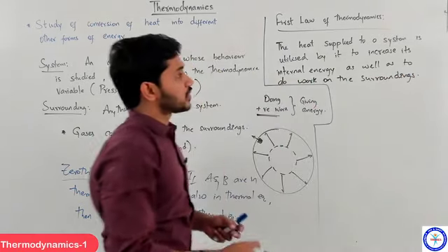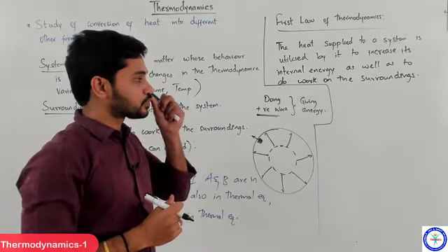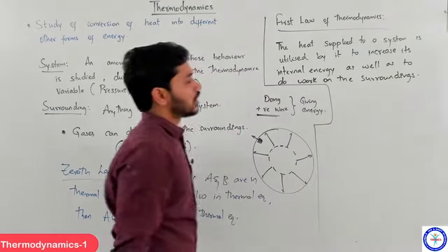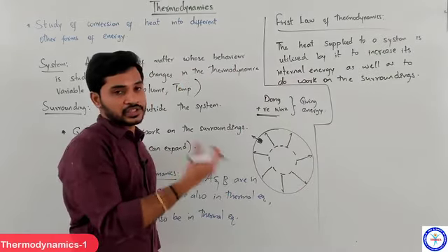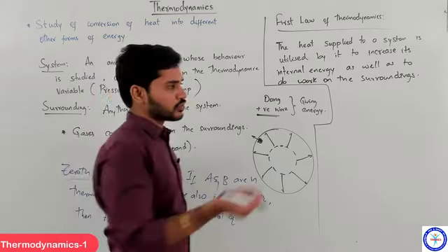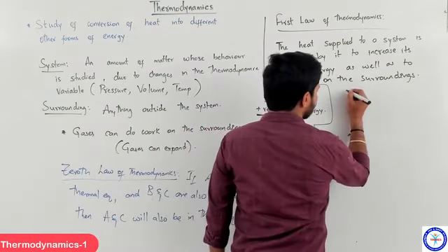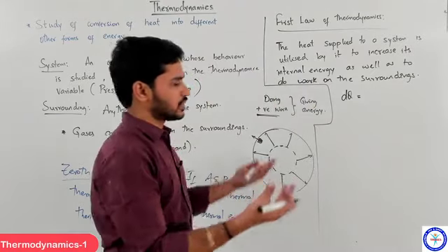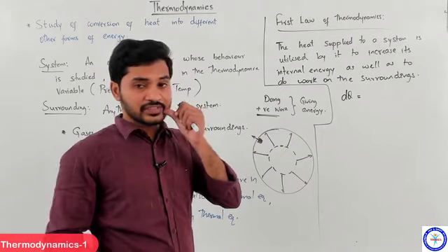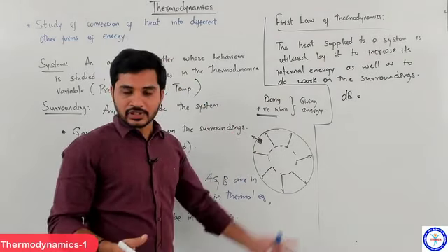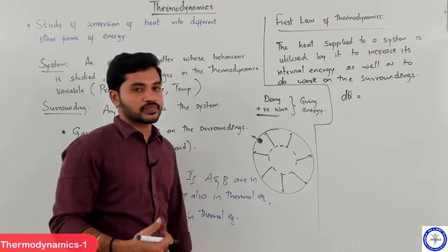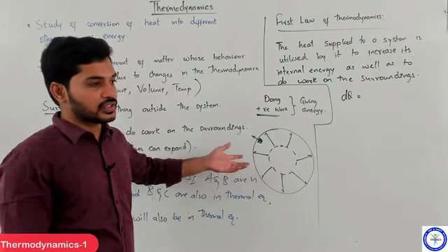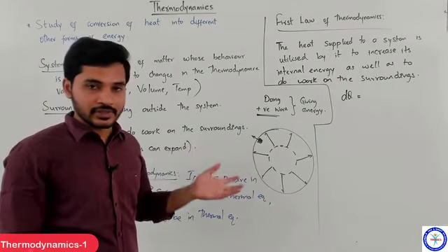Yeah, this statement is what we call the first law of thermodynamics, and you can write the expression for this in this manner. If I represent the heat supplied, change in internal energy and work done in differential form, small amounts, I can write it like this: dq. If dq is the amount of heat that is given to a gas, or it could even be a solid or liquid as well, but as I told you, we'll be mostly dealing with gases in this topic, because the work done will be negligible in solids and liquids.